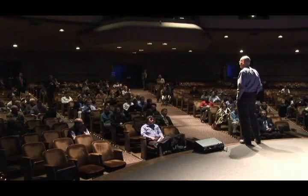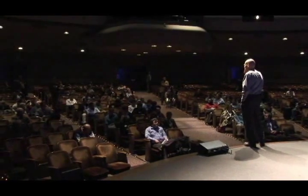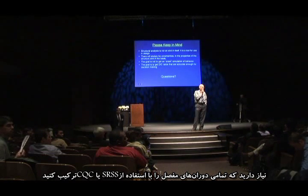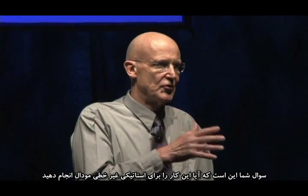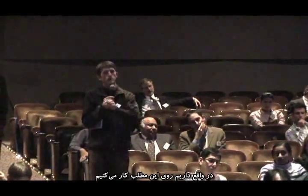Yeah, good question. Okay, and then another question regarding modal pushover analysis. In your earlier session, you talked about doing combinations. You can combine different pushover analyses to get results. For the modal pushover, you need to combine all the hinge rotations using either SRSS or CQC. Can you use the technique you were talking about earlier to do that for hinge rotations? There's a question there. Can you do the modal pushover where you do several pushover analyses for one? We're actually working on it.